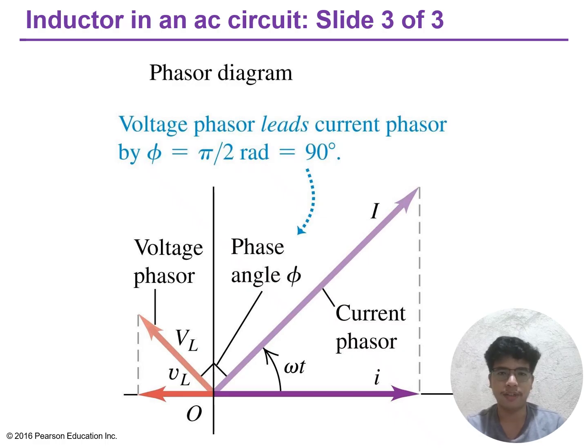The magnetic field within the inductor stores energy and releases it in a way that consistently delays the current relative to the applied voltage. For a student learning AC circuits, this phase shift is crucial. It explains why series inductors in a circuit produce currents that lag the applied voltage, and it demonstrates that circuit analysis in AC requires attention to phase relationships, not just amplitude or magnitude. The 90-degree separation is exact and unchanging across all frequencies, though the magnitude of the reactance changes.